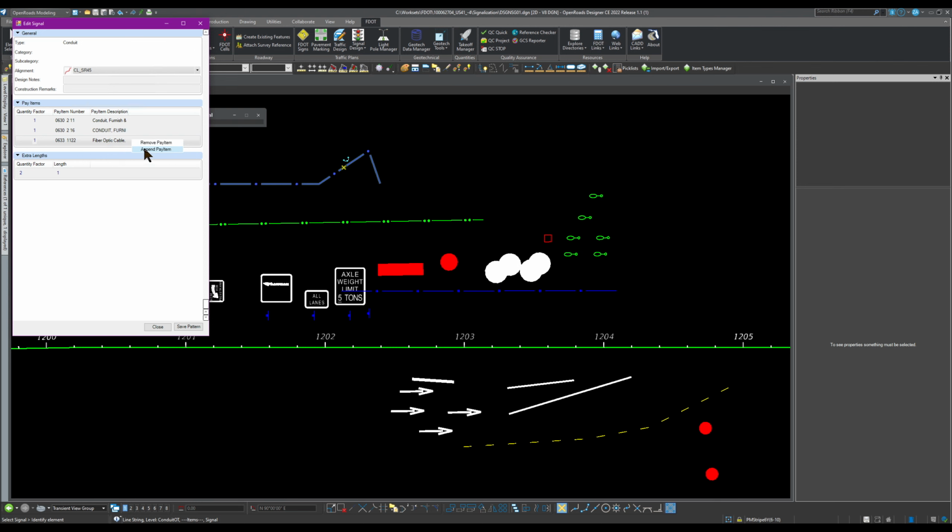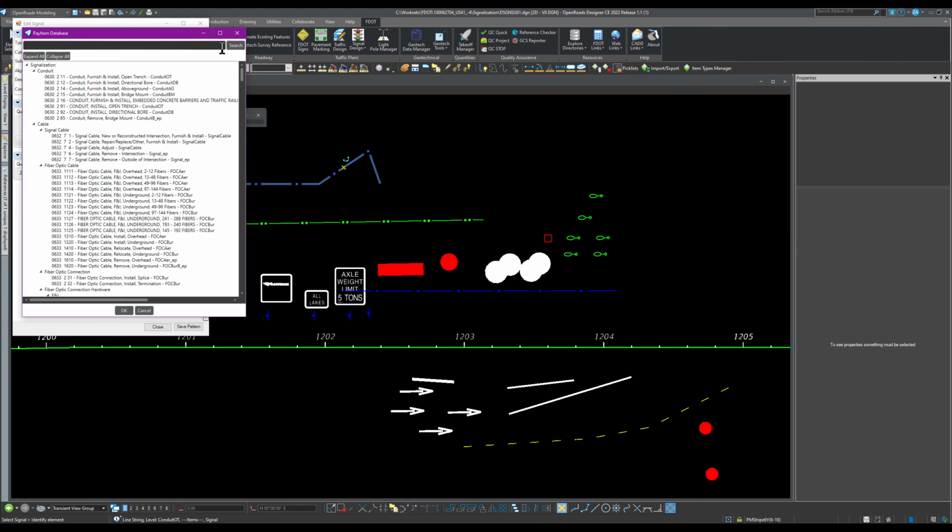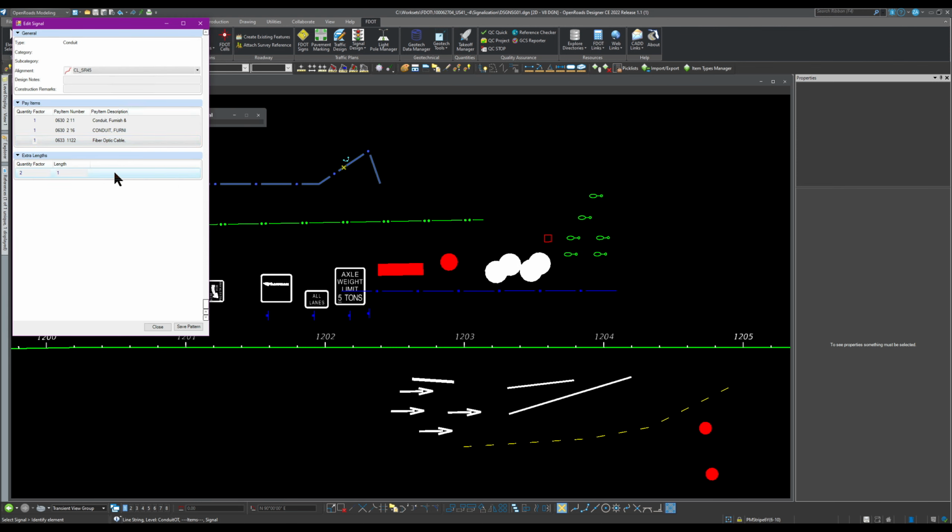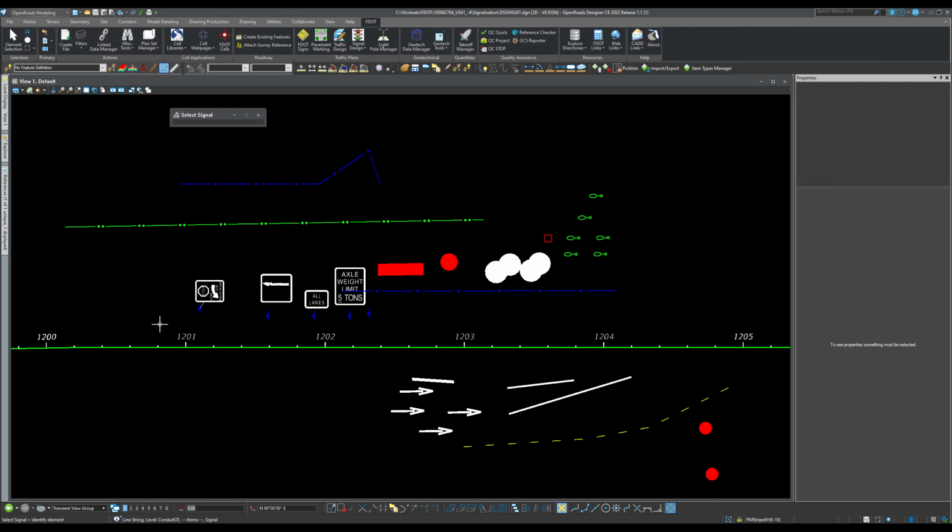If I click on append, it's just going to let me add it. But if I click on append extra, okay, I guess I have to do it like this. So it's going to apply this to this one, and it's going to apply, for example, the quantity factor 3, and this one I want it to be 1.2, and then close.